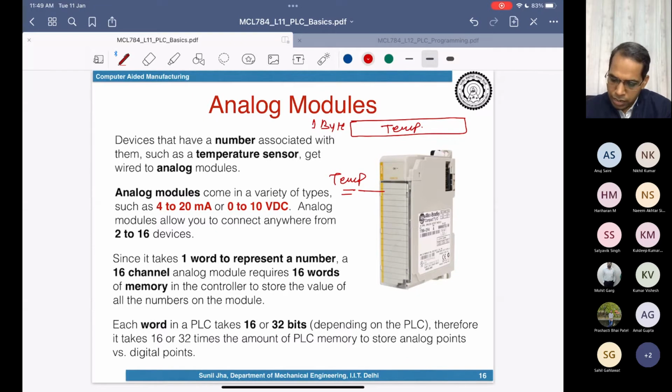Same, for example, if I have a pressure sensor over here, and I would like to store it as 10-bit resolution data, or it will be 12-bit data. Controllers internally may not have a 10-bit register or 12-bit register. So registers are always in multiples of 8 bits, because there's a byte and then there will be a word with 16 bits and then there is a 32-bit location.